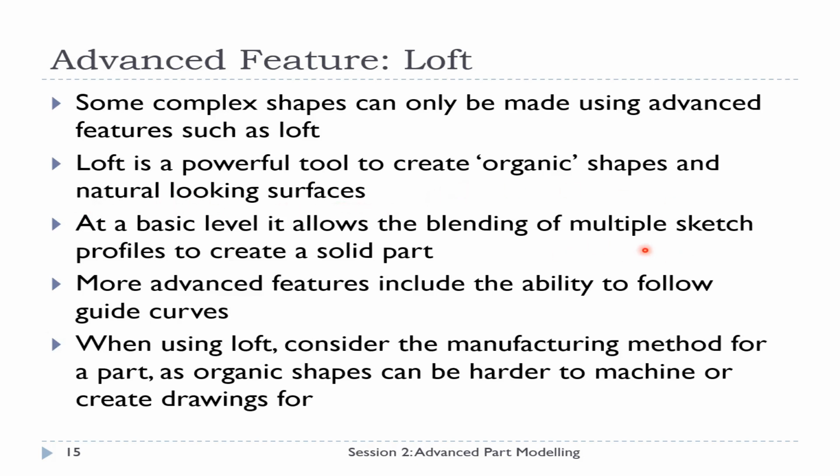So at basic level, it allows blending of multiple sketch profiles. It doesn't have to be only two different profiles. You can have a series of profiles to blend. And it's very advanced feature. We can use some guide curves to control how different profiles can be blended.